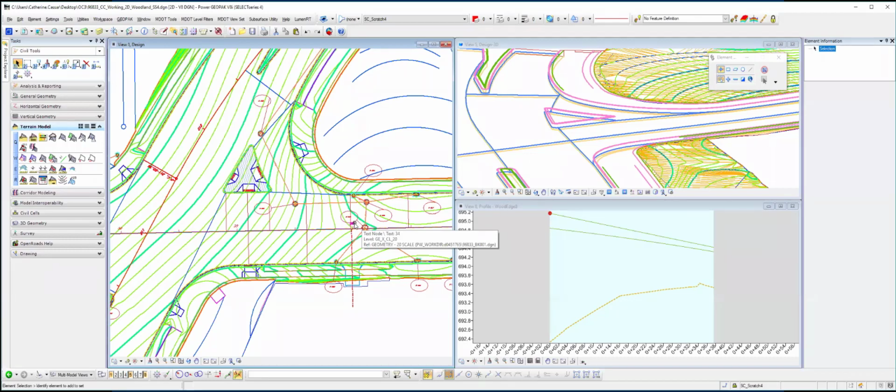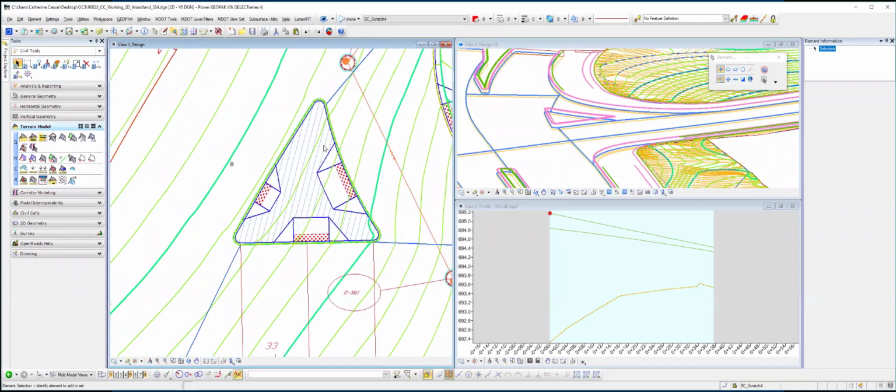I think it depends. It depends on what it's used for, right? Obviously, they're not going to do the grading with that. If you pavement all the way across, that might be misconstrued and not necessarily representative of what you're doing there. From a subgrade, if you need the subgrade for any reason, then that might be a reason that you might want to see that information so you know where the bottom of curb is.